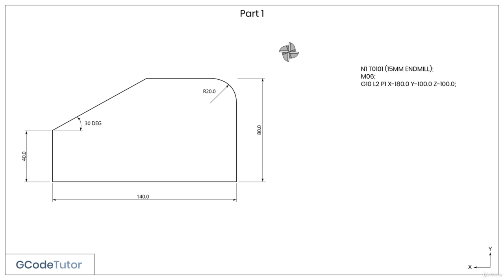Here is our G10 line. You should be slightly familiar with this by now. Our G10 tells the machine that we wish to set the datum position. This is used if the billet of material is always loaded in the same position each time into the machine, if we have a standard vise that's fitted, or a fixture that's always loaded in exactly the same position.